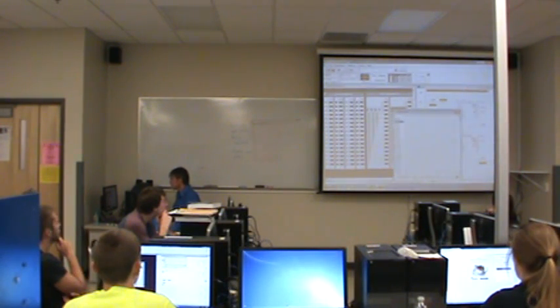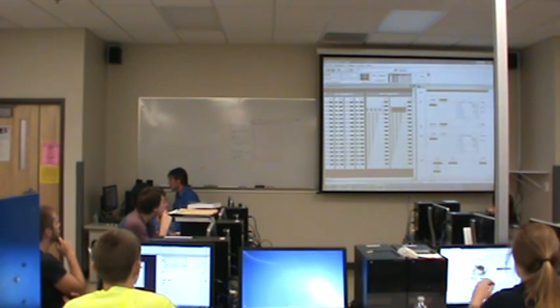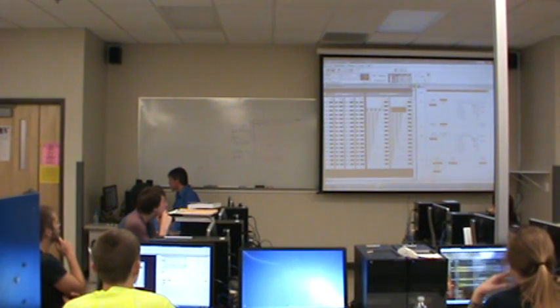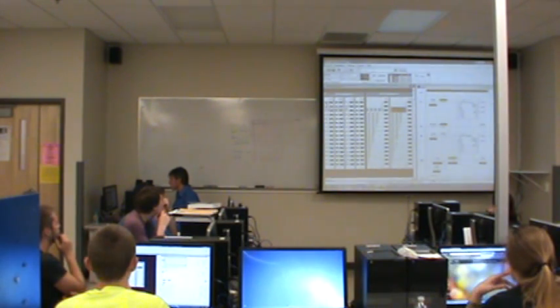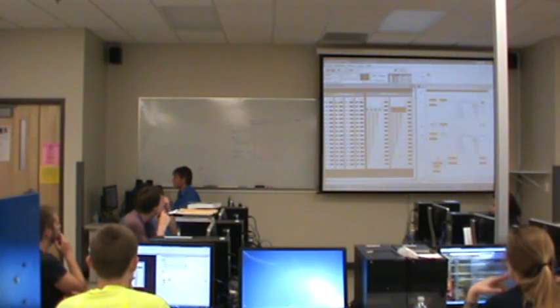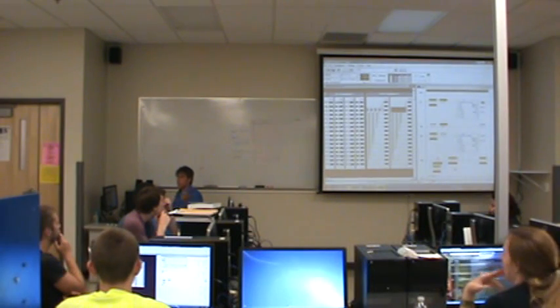Oh, well, I forgot there's one thing I added. I added a start-stop circuit, so we have to tell it to run. So we've got a stop button here and a start button here, so like normal. Now I'll do that. Now it's energized. Now it's actually looking. That's why I've got the run on here. These instructions weren't doing anything because I didn't have the system input.